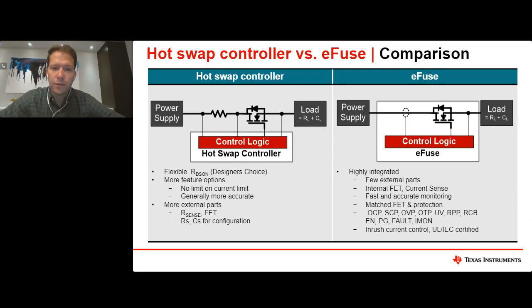Before we go over to our eFuse content, I just wanted to provide an overview of what the difference is between a hot swap controller and an eFuse. The main difference is that a hot swap controller controls an external FET and provides a lot more flexibility in terms of the RDS(on) of your FET. The eFuse, on the other hand, provides a very optimized solution, which can help you save board space and cost in the system. But in terms of protection features, the devices offer the same protection.